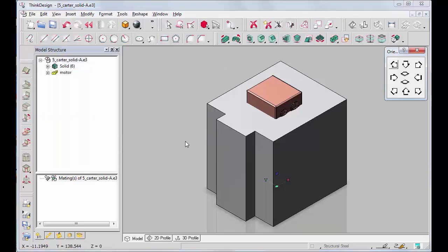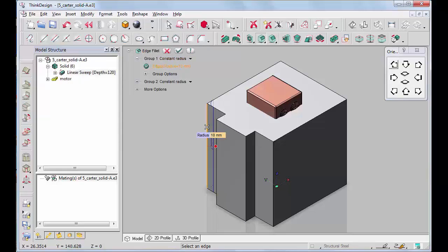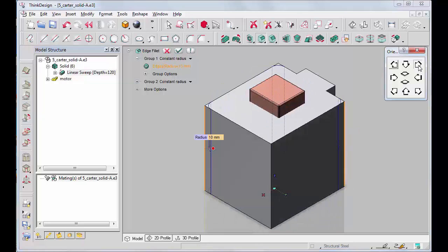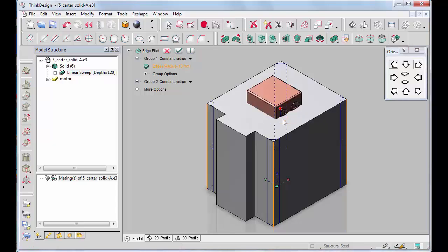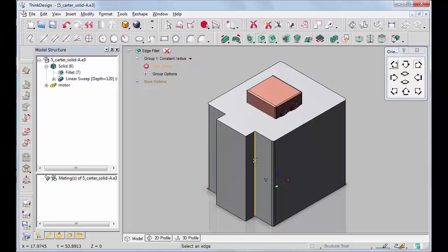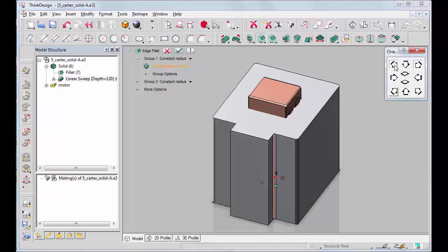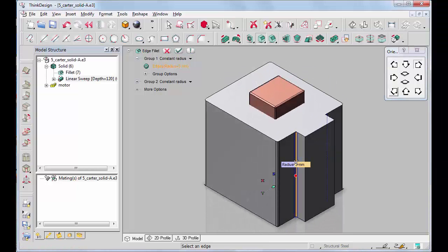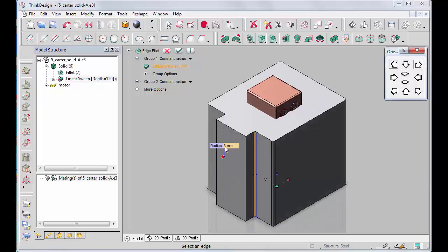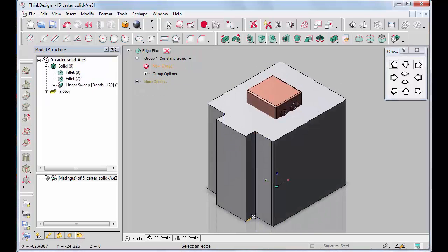Let's go on creating the fillets, first on the edges that are going to be the external bends using the edge fillet command. Let's assign the fillet on the outermost edges a 3 mm radius. We're rotating the model to see which these edges are, and the 1 mm radius to the fillets on the edges that are going to be the internal bends. Eventually, when we're done with the external fillets, let's assign the fillet of the base edge of the solid a 3 mm radius.